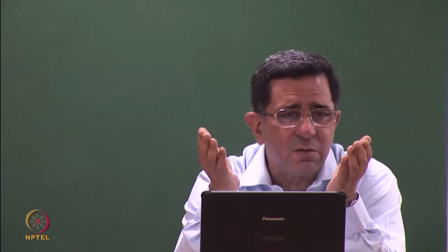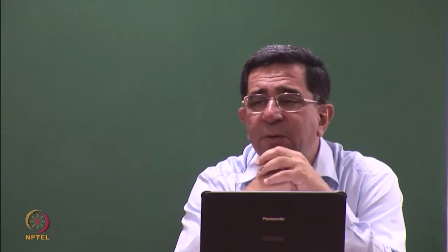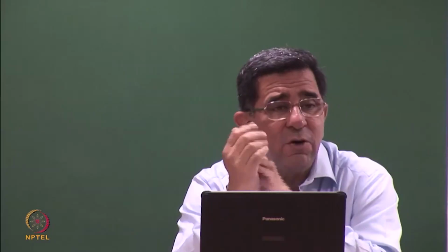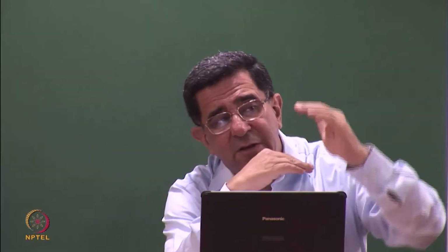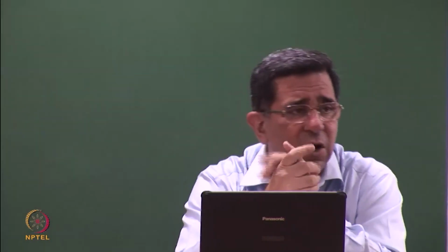Typically 6 inch thick is the minimum thickness which you can lay with the earth moving equipment. And 8 to 9 inches are the norm. And 1 foot is good, very good. And from the point of view of root zone penetration also 1 foot is a good thumb rule. But if you want to put shrubs whose roots are going to be deeper, then you'll have to put thicker covers. So this play-off between the thickness of the cover as an erosion control measure versus the additional cost of the local soil is something where you have a trade-off.